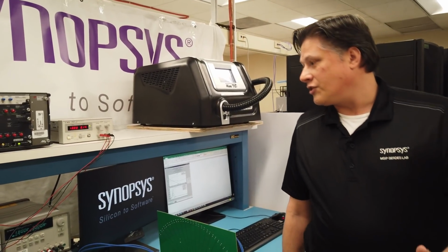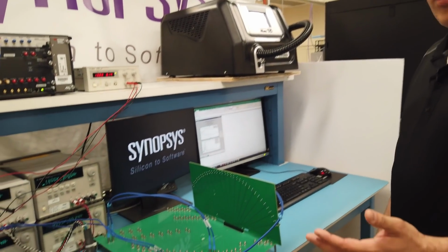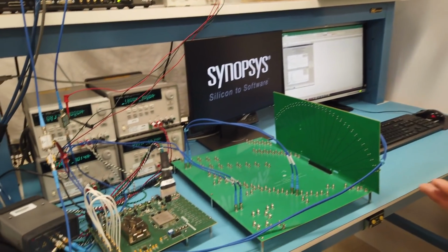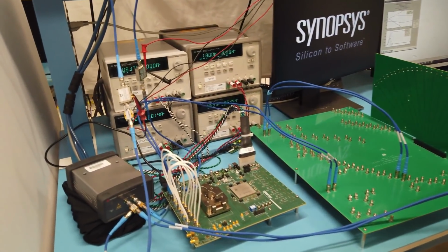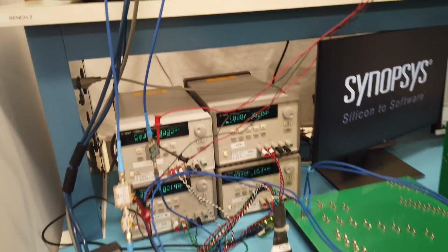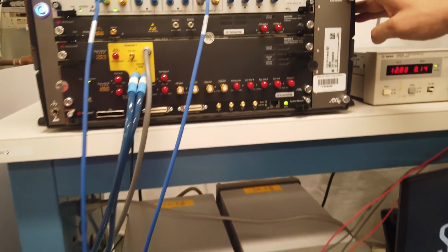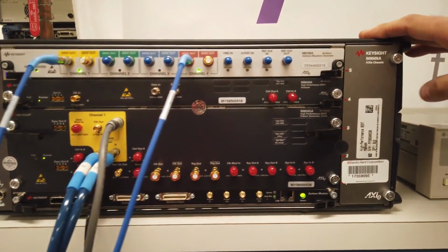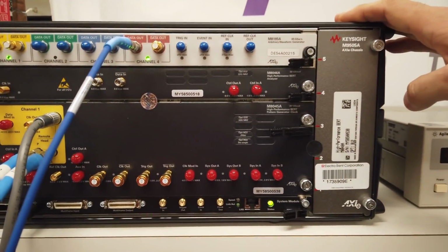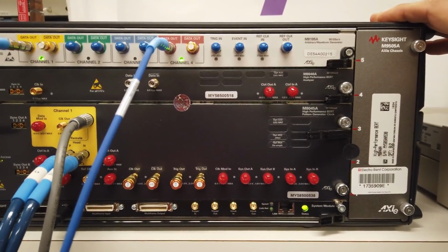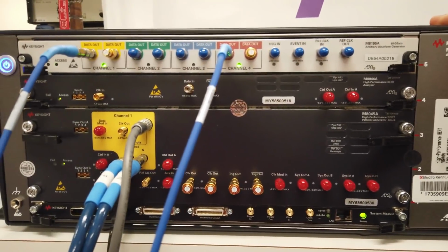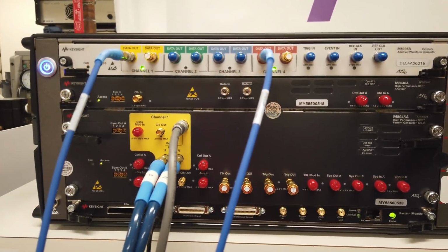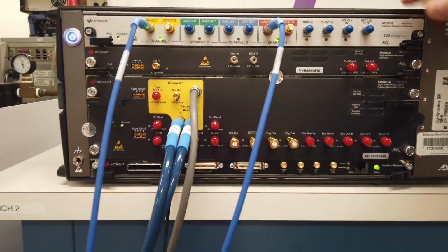Here I've got the receiver jitter tolerance set up. It's calibrated to the 5.0 version of the spec, release 1.0. And we've got a Keysight BERT 8040 set up with the impairments that the test requires: common mode interference, differential mode interference, random jitter, periodic jitter, and sinusoidal jitter. It's transmitting through the cables into an ISI channel.